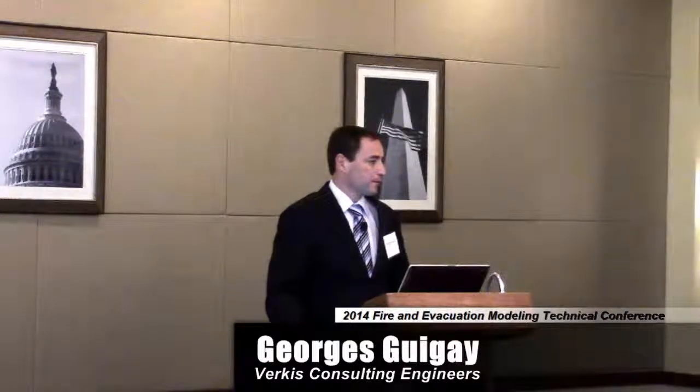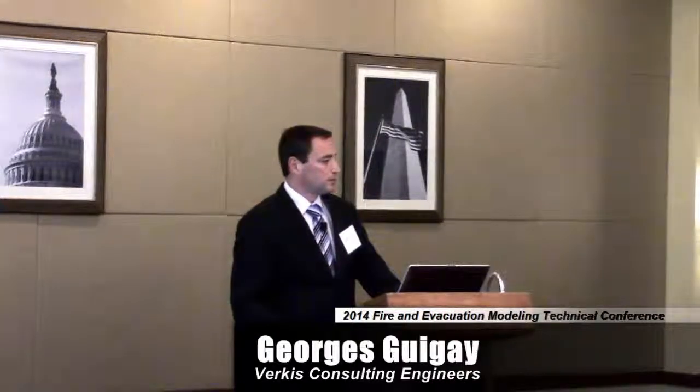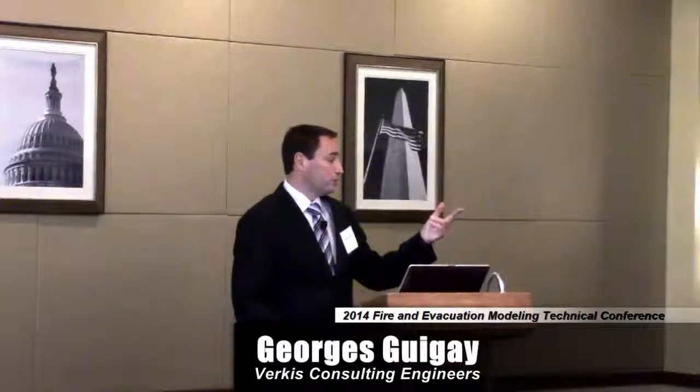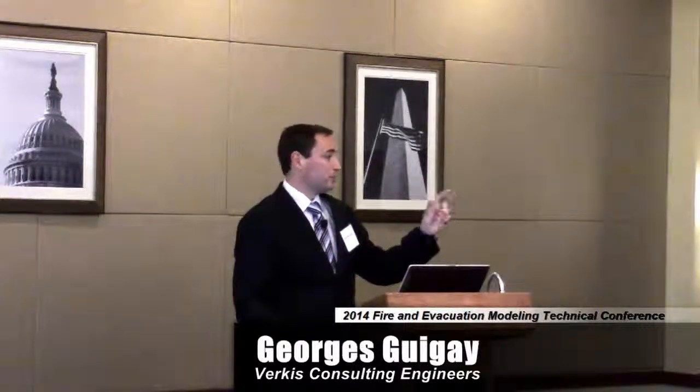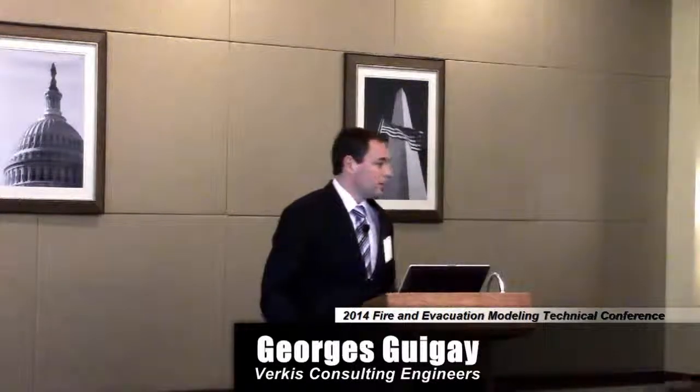So that's going to dilute the plume more, which is going to tend to lower the temperatures a little bit more. It's going to increase the layer depth because you're entraining more volume. That may be consistent with what you're seeing, but again, it's going to depend case by case. But if I had to guess why you're seeing the results you're seeing, that would be my guess. Yes, I should have maybe checked the temperature a little bit more to see if my layer in FDS5 was slightly colder than in FDS6.